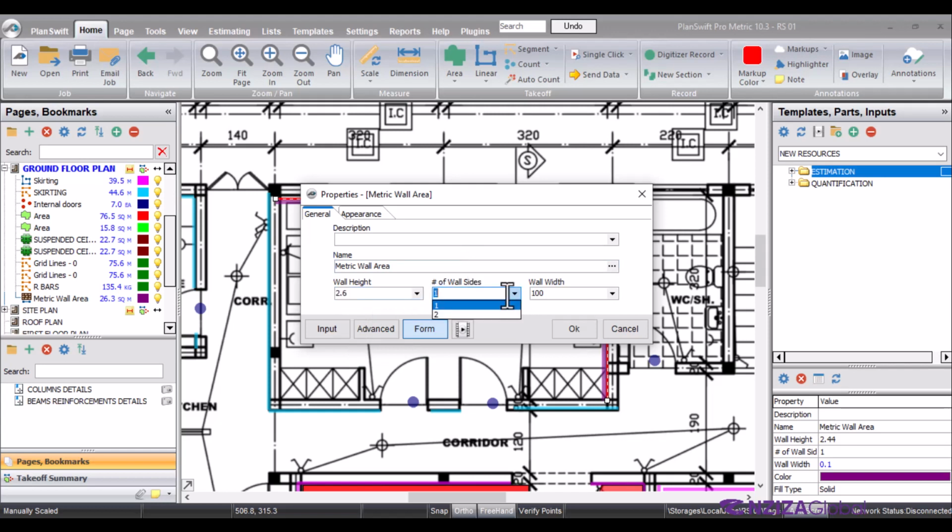And if you have a number of them too, it gets doubled. If the wall width is changed, it doesn't change the quantities, but maybe it can change the pricing and the specifications as well. So this is how you measure the wall area. But remember, we need to care about deductions of doors and windows. These we are going to see in the templates lecture.